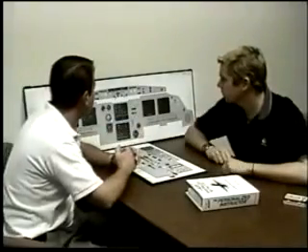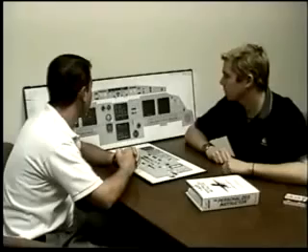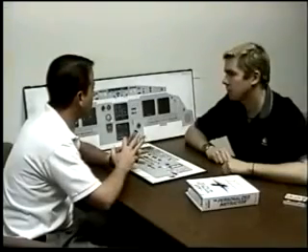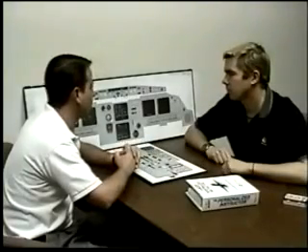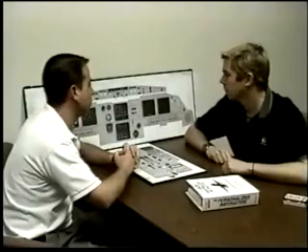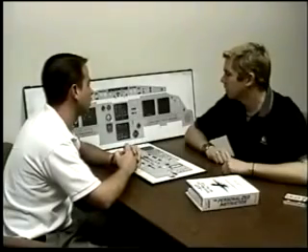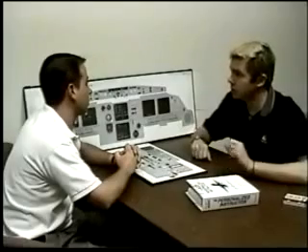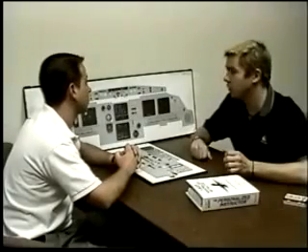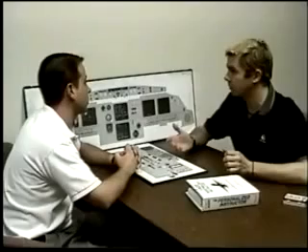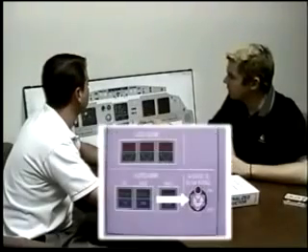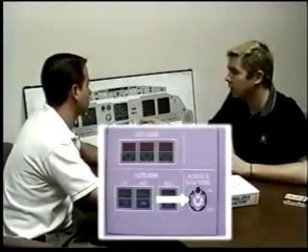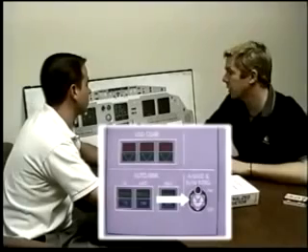New day, you're taxiing out, captain goes to do a brake check, should have normal brakes, applies the brakes, and the airplane's not stopping. What might you do? And what are some cautions to doing this? Sure. Well, the first thing I do is get off the brakes, and then I'd also make sure I don't have any steering inputs in there, because when I do the next step, I'm going to get rid of my nose wheel steering. I'll reach up, turn the anti-skid nose wheel steering switch to off in hopes that the alternate brakes are going to stop the aircraft.